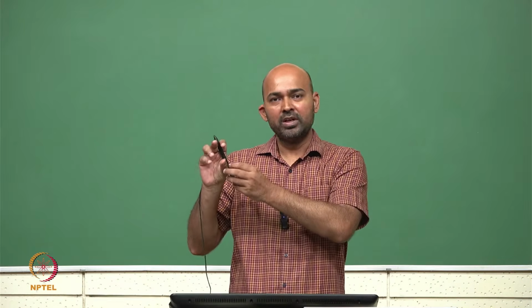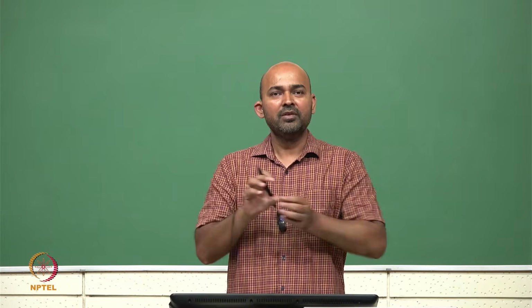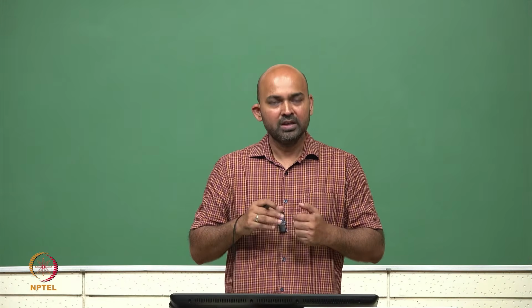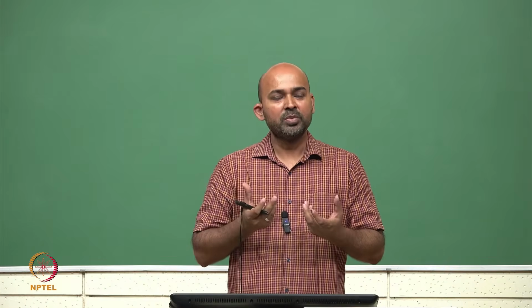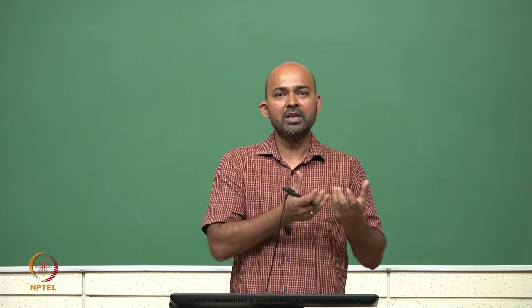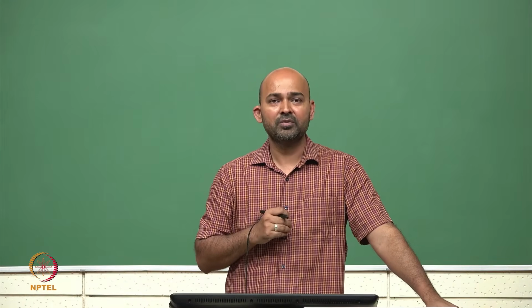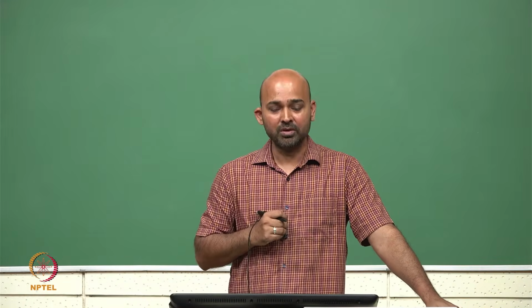With two voltage sources, we consider only one voltage source, shorting the other voltage sources and open circuiting all current sources. We take one at a time and compute the voltage at the load, and then take the algebraic sum of all the voltages. So the total voltage will be the sum of all those individual voltages. This is what the superposition theorem says. The limitation of this theorem is that all components we use in our circuit should be linear. That is a fairly good assumption for the superposition theorem.